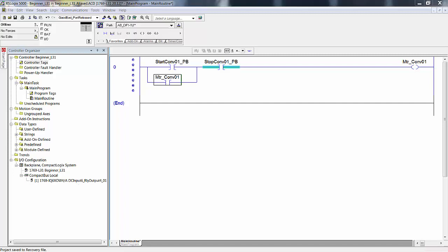What we mean by data scattering is, for troubleshooting purposes and programming purposes, it's good if all of the inputs associated with that conveyor, conveyor 1, are all on the same module in sequence, and they're contiguous, meaning that there's no gaps in between them. That's what we mean by preventing data scattering. It is even better if you write the bulk of your program before I/O assignments, thus allowing the most logical, contiguous I/O assignment possible.